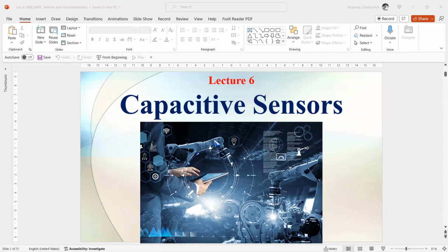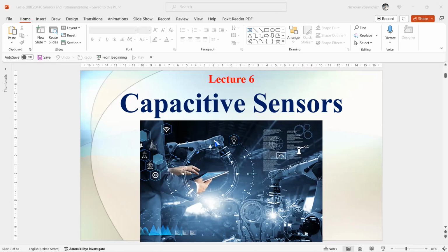We will focus in particular on nonlinear and angular displacement sensors and on force sensors too. Next, integrated silicon capacitive sensors are briefly reviewed, and some interface circuits are given to measure small capacitance changes.